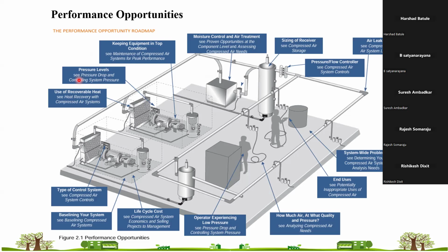Okay, and also I have to feed fresh water again. Otherwise, my delta T will not be maintained. Suppose in my washing machine example, with this water recirculation and delta T, if it is not recovering that much heat, then my compressor performance will again deteriorate because of the high inlet water temperature, maybe around 55 degrees. That's where you need to design a buffer tank, you need to design good water flow. The entire system has to be designed like that.